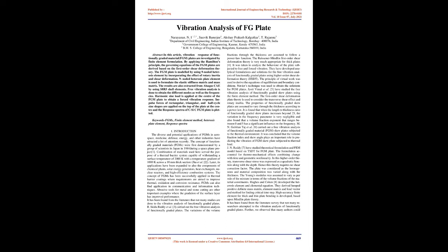The results are also extracted from Abaqus CAE by using S8R5 shell elements. Free vibration analysis is done to obtain the different modes as well as the frequencies. Harmonic sine load is applied at the center of the FGM plate to obtain a forced vibration response.